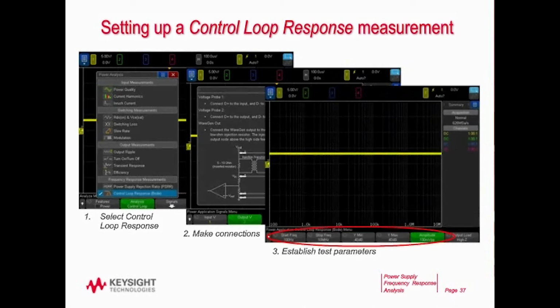Now, I don't know if you can read it or not. The amplitude there says 130 millivolts peak to peak. At this setting, the scope's generator thinks it's driving a high impedance output, but it's not. That isolation transformer has about an effective 5 ohm input impedance. And so the actual voltage that's going to be across the input of that one-to-one transformer is only going to be about 12 millivolts peak to peak. So we're driving it with a very low-level signal. Again, if you don't have this, our scopes, the InfiniVision X Series, don't have this option built into it. If you're using an external scope, external generator, you can do this with LabVIEW and MATLAB.